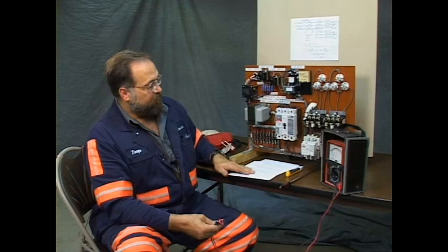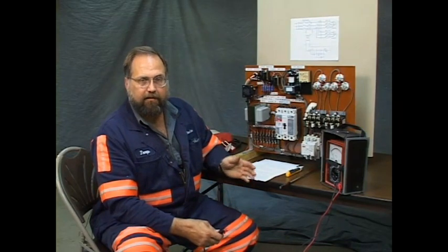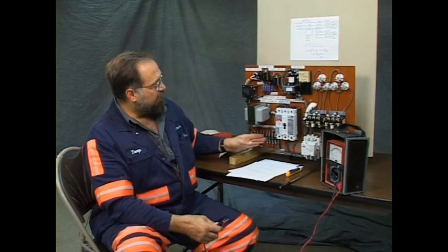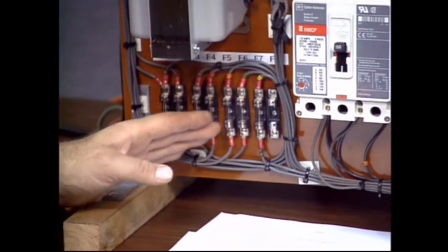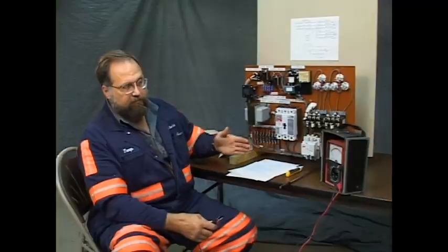As you can see, we've had the first 4 problems. 3 of those have been motors will not run, and they've all been different problems. Ours have been open wires. It could very easily have been an open fuse. But by checking in this fashion from the line side of the fuse to the load side of the fuse, if the fuse is open, it will be determined.